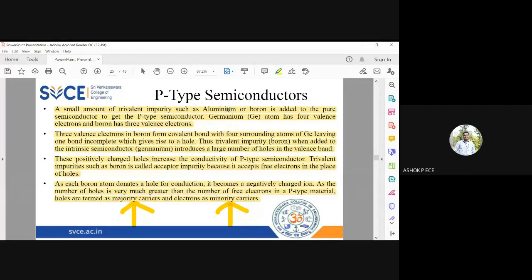And what is group 4? Group 3 and group 5 are your impurities or your doping elements. What is group 4? Yes, somebody told the answer. Silicon and germanium. Yes, silicon and germanium belong to group 4. So elements in group 4 are predominantly semiconductors, and on either side of group 4, group 3 and group 5, they are going to be our doping agents. Group 3, if I dope, I will get p-type. Group 5, if I dope, I will be getting n-type.